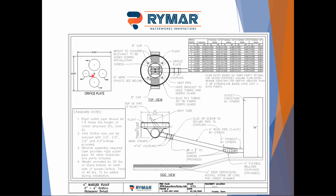This orifice plate has a small hole in the middle, and there's a small nub that sits right here that this fits over. You just turn it so that the right orifice size fits over the outlet. In this case, you'd have a 4-inch outlet, and you'd have 2-inch, 2.5, 3, and 4-inch orifices in here. We have a 4-inch orifice, so you can just leave the orifice plate in there so they don't lose it and get the 4-inch full flow. Some of the skimmers have different sizes, and you just take the orifice out for full flow. But anyway, it's a really easy, convenient way to change the flow rate.